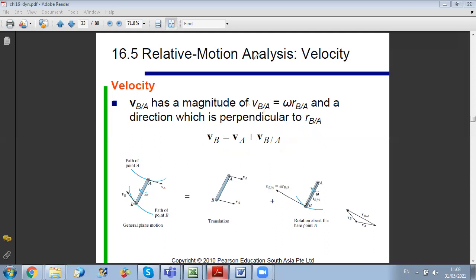So as a first rule, whenever I have one rigid body and 2 points of the same body, okay, so you don't have relative motion between the 2 points, the distance between the 2 points is fixed, okay, then you will use a translating frame. However, if you have, for example, a person on a body and this person is able to move on the body, then we will use the concept of rotating frame. We will see why. Because in this case, this point will be able to move on the body, will have a freedom of motion. However, when you take 2 points of the same body, the distance between them cannot change.